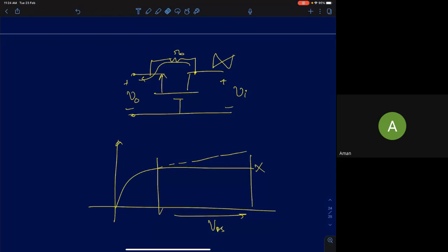See, understand, one of you is asking a question: isn't the device a symmetric device? But you should understand the idea of being symmetric will hold true only in digital design. In analog design, once you bias a transistor, drain voltage will always be greater than source voltage, which means drain is fixed, source is fixed.